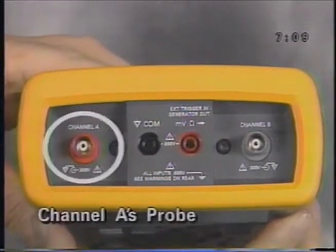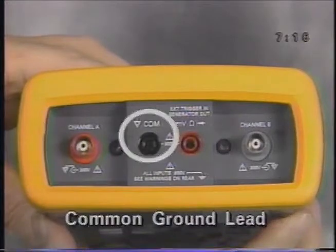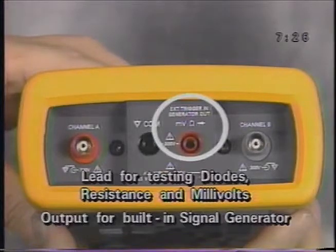The red BNC jack is for channel A's probe. The gray BNC jack is for channel B's probe. The black banana jack accepts a common ground lead. The red banana jack accepts a lead for testing diodes, measuring resistance in millivolts, and is the output for Scopemeter's built-in signal generator.